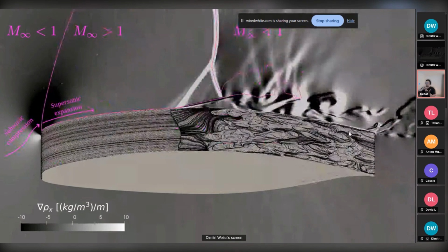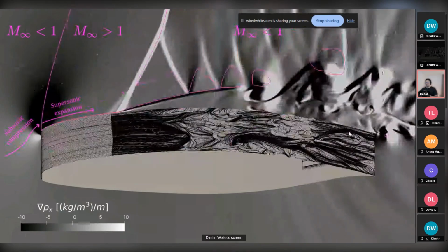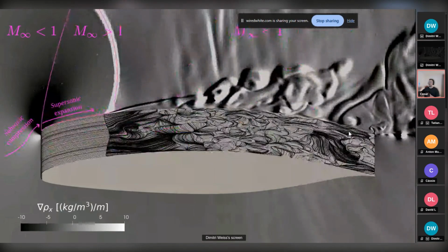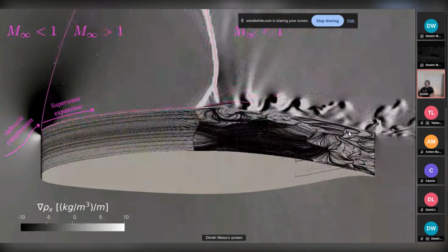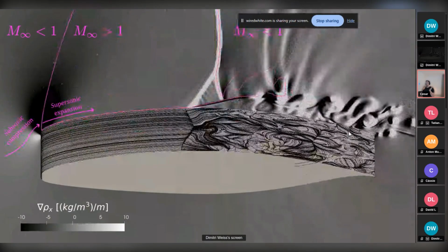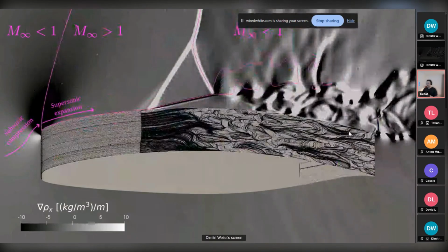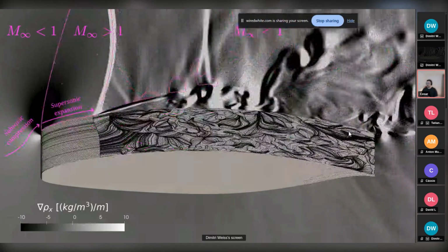However, due to the curvature effects, the rise of pressure by the shock presence, and the flow instability coming from the wake, this causes a massive separation, and that's why we can see the alternating pattern between a fully attached and a fully separated flow.